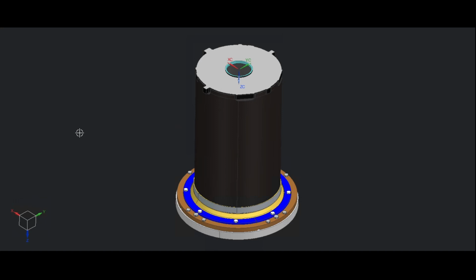Then 12 bolts between the clamping band and the interface plate. These ones. And 16 more bolts between the interface plate and the shaker table, which go on the bottom into these threaded holes. In the finite element model, the bolts are modeled with the most common element type, which is a 1D spring element with 6 degrees of freedom.